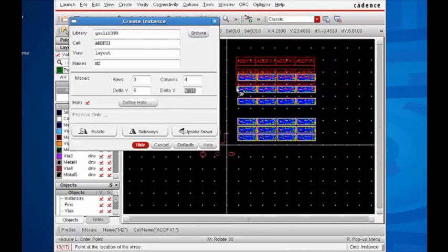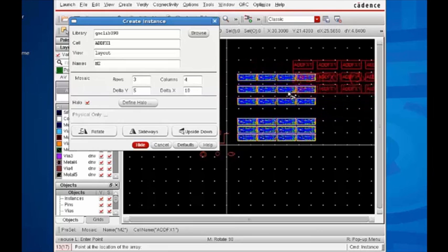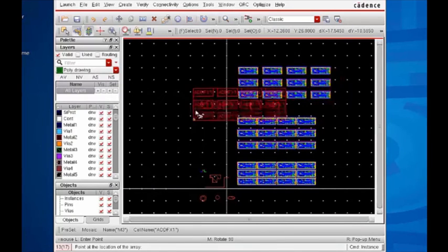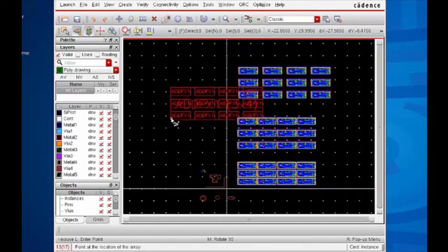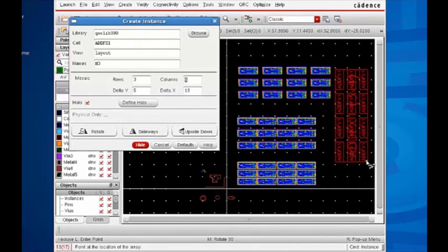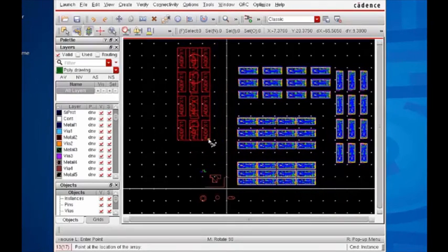Let's bring the F3 back up. Just change this to a distance of 10. Click in another one. Come back in, and use the arrow to select, use the arrow to come up. Now look what we've got. And then let's do F3 once again, and let's say rotate, and then come back in, and notice that the entire array has rotated around 0. So they didn't individually rotate. At the 0 point, the entire array rotated.